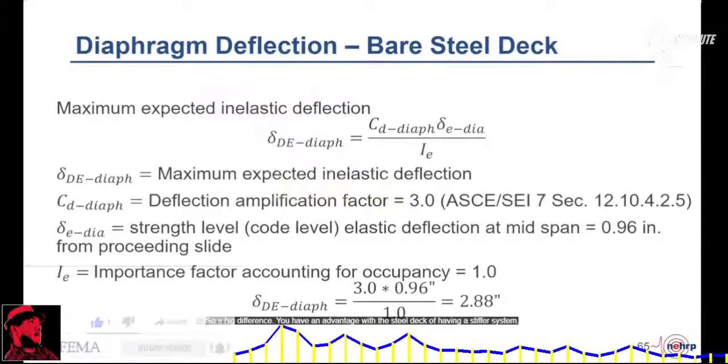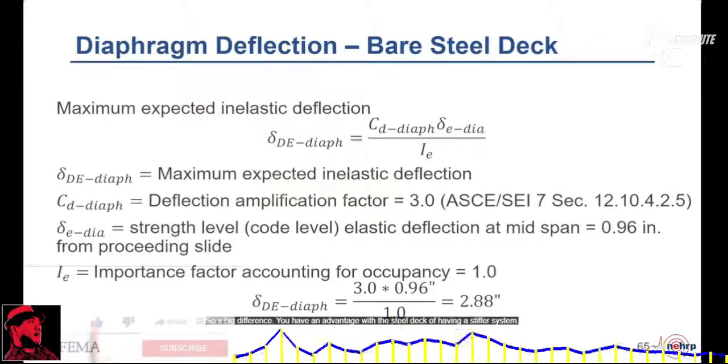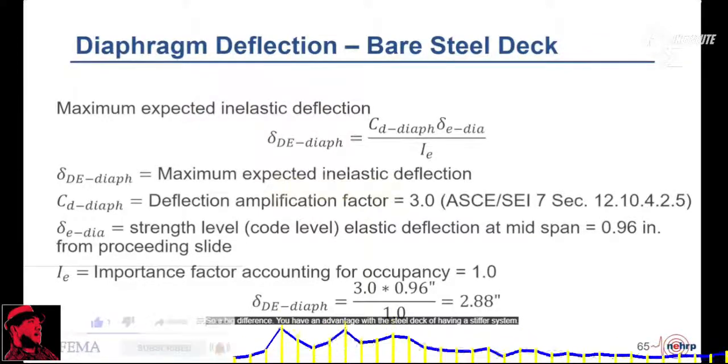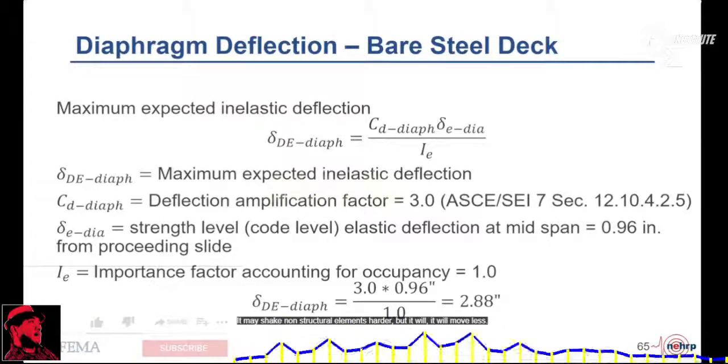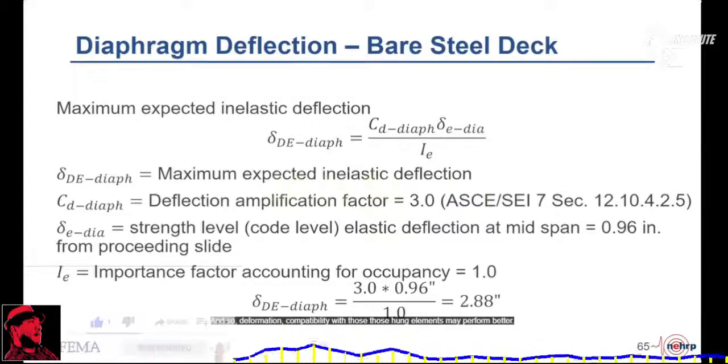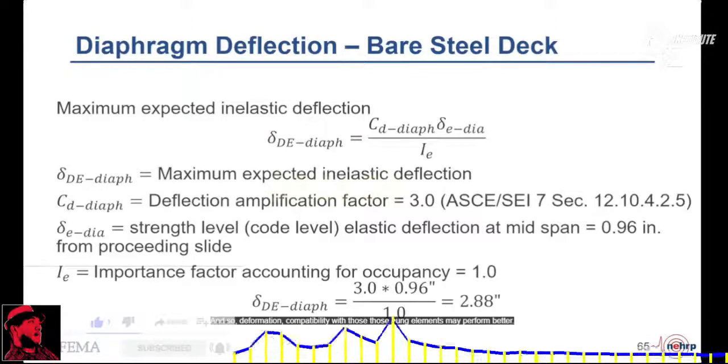So you have an advantage with the steel deck of having a stiffer system. It may shake non-structural elements harder, but it will move less. And so deformation compatibility with those hung elements may perform better.